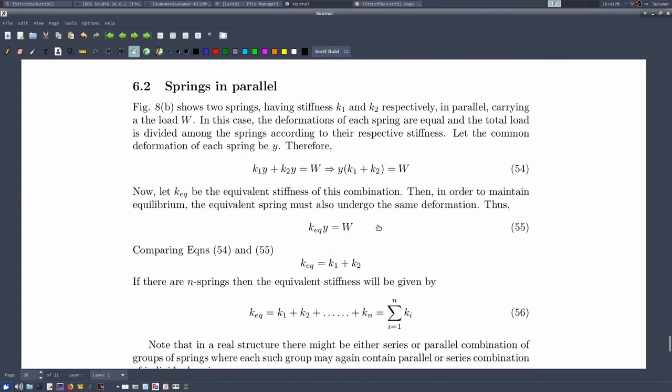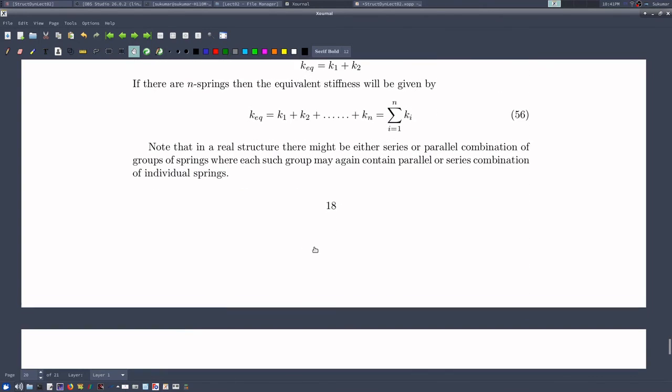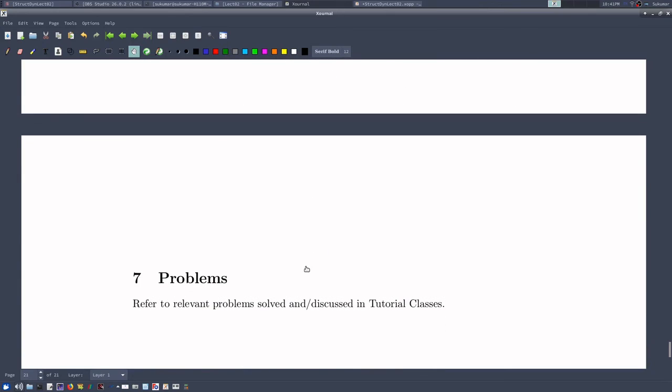And this is the case of resistances connected in series. So the spring case is just opposite to the combination of resistances. Therefore, in case of parallel springs, to get the equivalent spring constant, I can simply add their individual spring constants. And in case of series combination, I have to add the reciprocals. That is the only difference. So this is how equivalent springs are obtained.